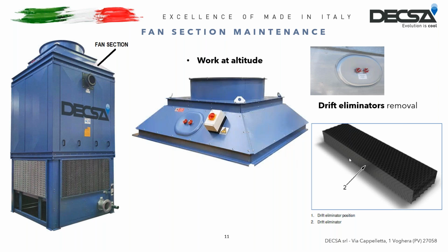After this last check, we can reposition the drift eliminators, close the inspection door, and start the motor to return to 100% operating.